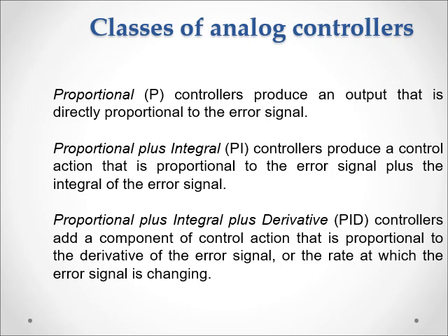Now, to overcome this problem, let's talk about, instead of a multiplying factor, why not just use an addition factor? That is, we just add the error over time. That is how the integral part comes. When you have a kp value at a certain level, you will have a steady state error because you cannot overcome this small error. But if you add up this error over time, that will have enough actuation strength to overcome this error, but not too high a strength that will cause vibration to the system. So that's why you have a PI controller.